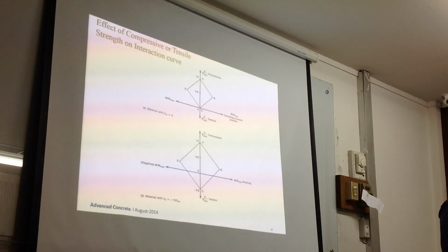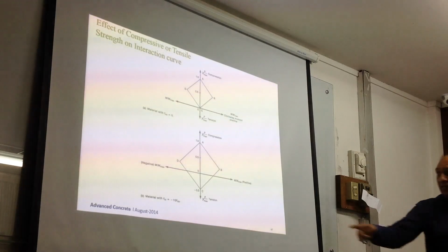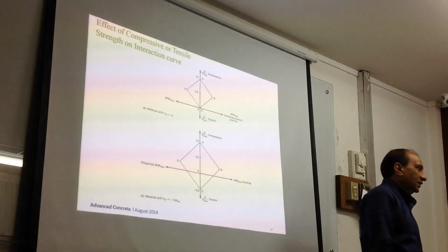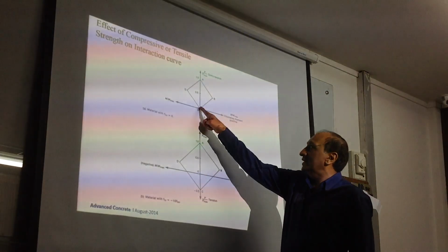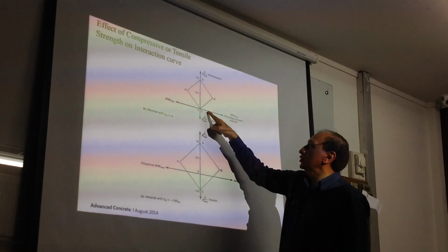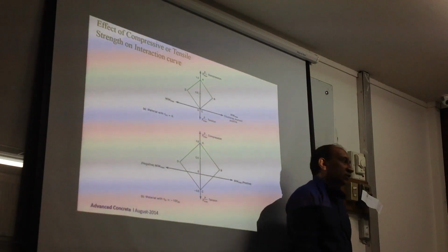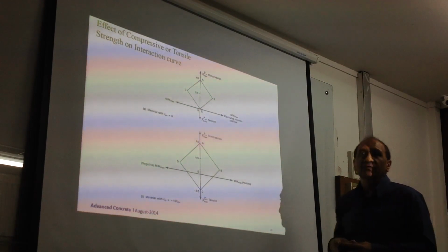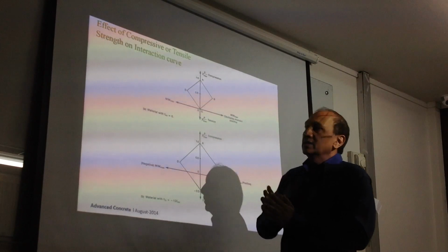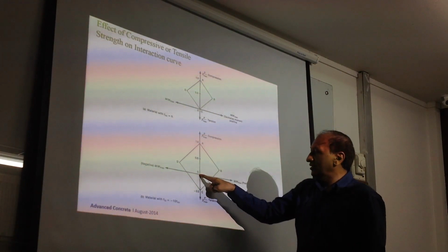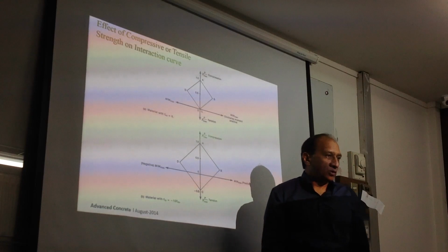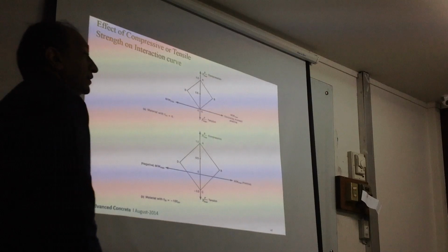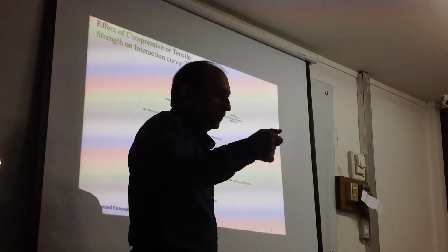So if you are expecting negative P, tension, then you need the negative portion of the curve. Otherwise, it won't work, right? And also you can see from here that at this point, the relationship is such that you may not be able to get the ratio that you are looking for. So that's why we need some reinforcement. At zero moment, you still need some capacity, right? So we need some reinforcement to work with that. Otherwise, there may not be any capacity for zero load and zero moment.